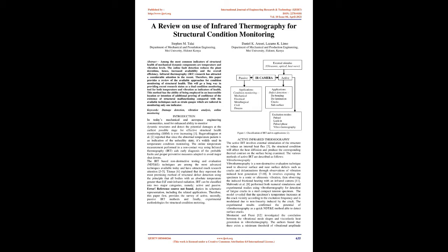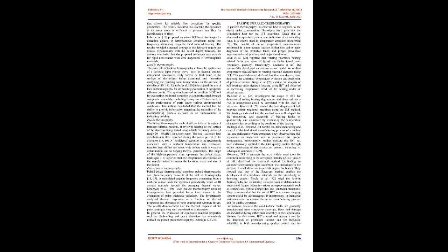Active infrared thermography. The active IRT involves external stimulation of the structure to induce an internal heat flux. The structural condition will affect the heat diffusion and produce the corresponding thermal contrast on the surface being examined. The various methods of active IRT are described as follows.